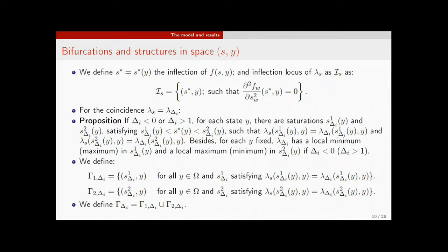The inflection curve for saturation has this expression, and this consists of two surfaces associated with solving this equation. This is important because this structure implies that the saturations, Buckley-Leverett saturation, stop at this inflection point.